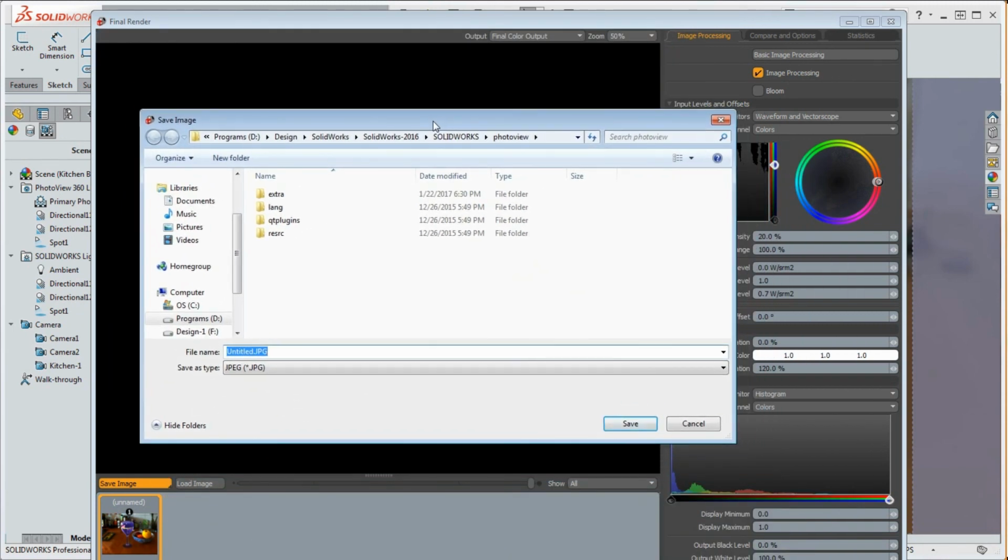What we talked about in this latter part of the video is some of the display options that were available in here. We talked about some of the appearance settings with regard to putting on frosted glass and then coloring the glass. Then we put in a decal and all the settings associated with the decal. Then we finally ended up with scenes and lights until we got something. Once we put our render together, after looking at the preview window, we got something that we thought was pretty good. And there's a lot of options associated with that. Try to make it look as attractive as you can, and then send me that image when you're all done. And of course, you're going to be satisfied with the image too. You're going to put that into your cover sheet of your drawing set.